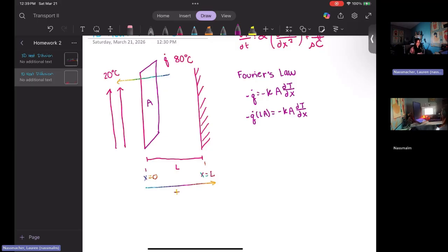What this equation is telling us is that the heat loss will be equivalent to the heat generated within our slab. Now, if you think about the temperature profile, it will create this curve and end in a straight line where the slab is insulated. We know this from a previous video where we explained how we can gain this temperature profile by learning about how the heat flows through the slab.